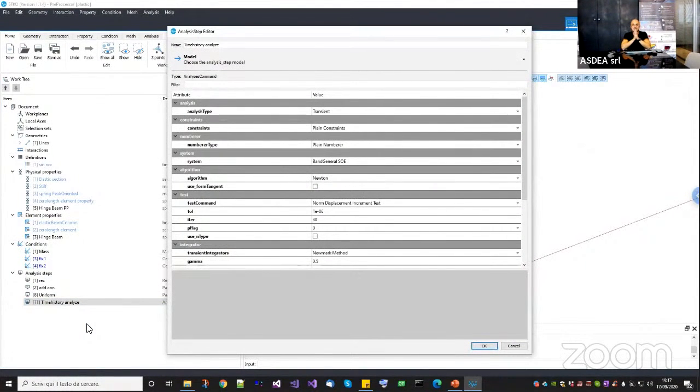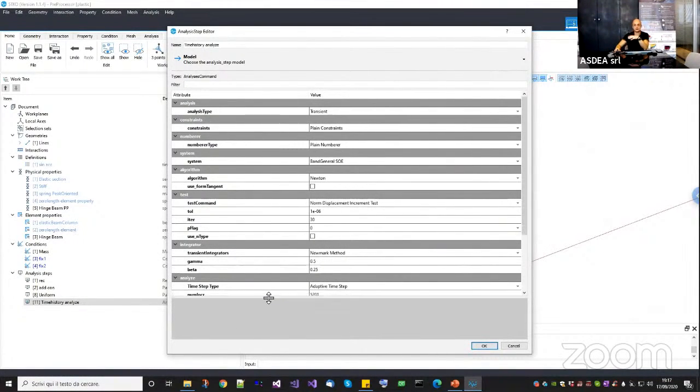Here I will give you the settings that are not working, okay? If you have followed our other webinars, we were always using the displacement increment test with values to the power of -5, -6. And if you think about it, it may seem reasonable because you are modeling in meters.